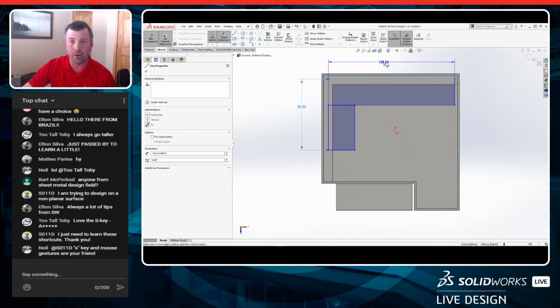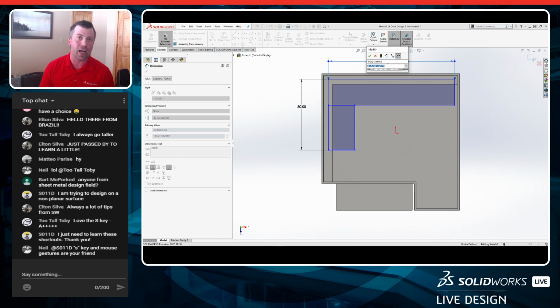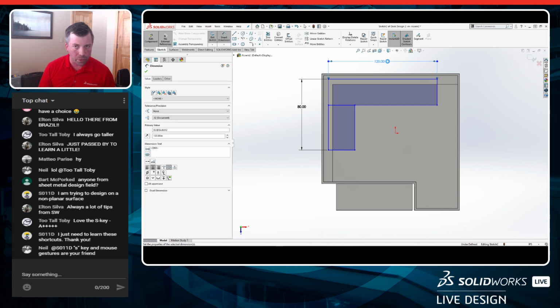Now up here, I also wanted to be as economical in time and money as I could. So I went to just 10-foot long standard pieces of 2x4 to build out the bottom box. So I just said, hey, what does 120 inches give me? It gave me enough room at the end to put in a file cabinet down the road if need be, or build in additional shelving. But that way I'm saving cuts. I can build the box based on that 120. And this is just that stock lumber size.